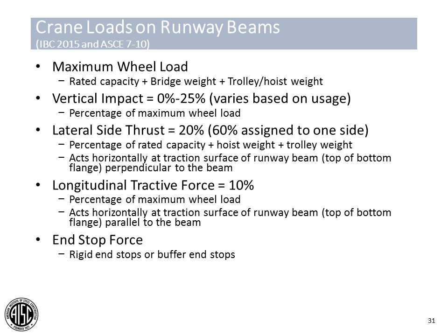So that's why this needs to be a consideration very early on in the project, because if you're designing this crane system late in the project and trying to integrate it into a structure, or trying to retrofit a structure with one of these crane systems, the deflection criteria is what's probably going to be governing your design, because you do need to design anything that's supporting that crane system for the crane system allowable deflection criteria.